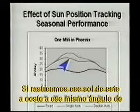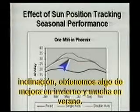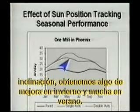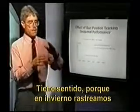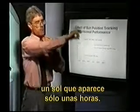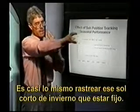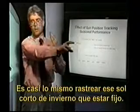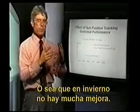If we track that sun east to west at that same tilt angle, we get some enhancement in the winter, a great deal of enhancement in the summer. That makes a lot of sense because in the winter, we're tracking a sun that's only up for a few hours. It's almost the same tracking that short winter sun or being fixed. So the enhancement isn't so great in the winter.